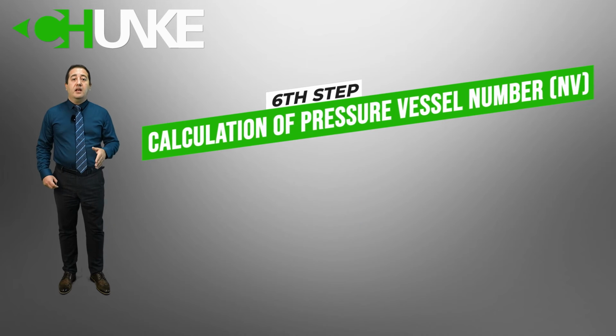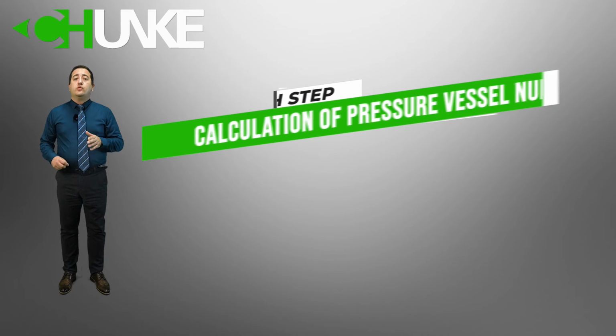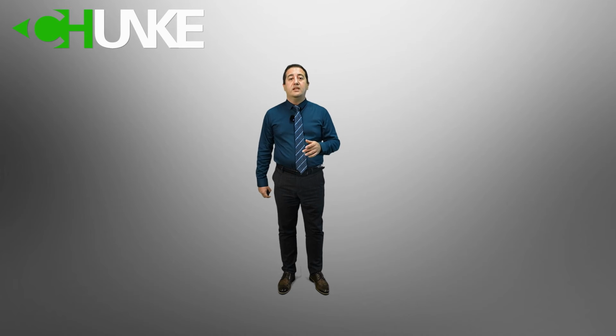Step 6. Calculation of pressure vessel number. Total number of pressure vessels needed equals total number of modules over number of modules in a pressure vessel. The calculated number should be rounded up to the nearest integer, such as if you find 5.89, you can use 6 vessels.